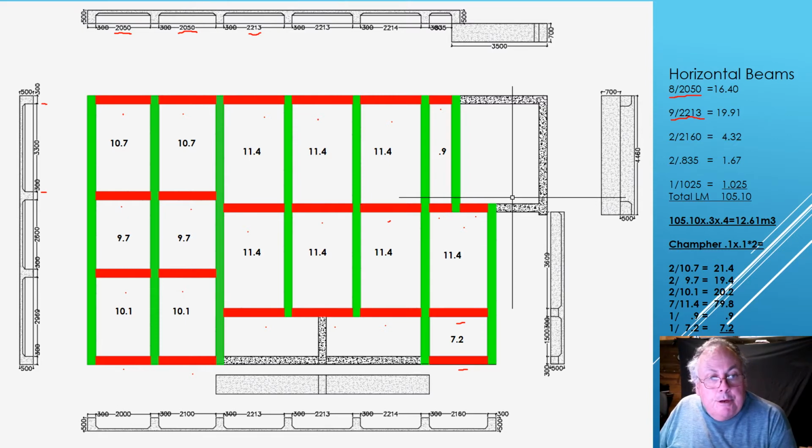The other part that's really important about this is, what are these figures here? Why would I actually put those in there? If we look right up here, you can see a little detail. It's like a little chamfer. It's 45 degrees roughly, and it's where the plastic drags over the edge of the soil down into the strip footing or the footing beam, and it creates a void which is actually quite a substantial amount of concrete, quite a realistic amount.